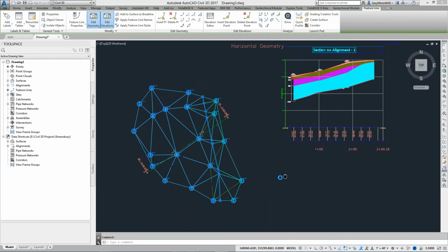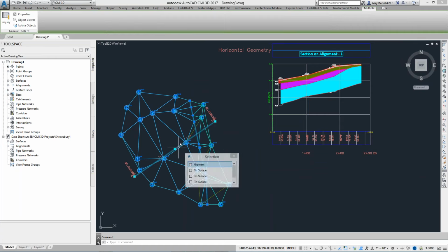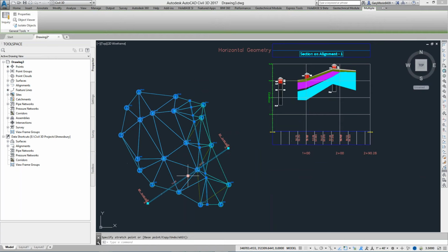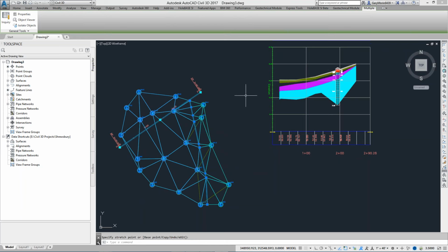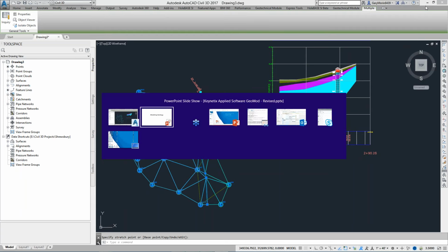I'll zoom in a little way so we can see it a little bit better. And the nice thing about this, if I now move that cross section to somewhere else, can you see where the gravel goes into the sandstone? It all pinches in correctly. Now you see there's more modeling I have to do, so it's the same principle again. I've been looking at how to model this geology for many years now in AutoCAD, and actually it is just that same principle, that and perhaps using boundaries, and that's all we use to actually model the data. So it's a pretty quick process. So we're just about done.